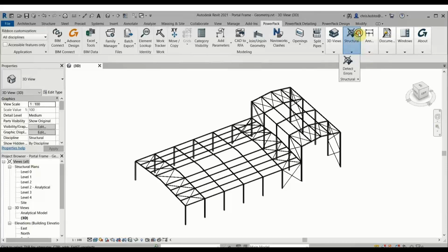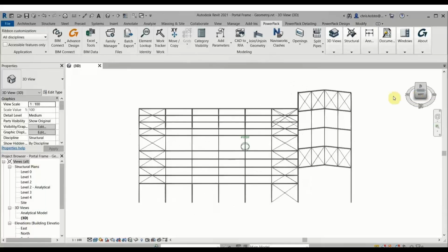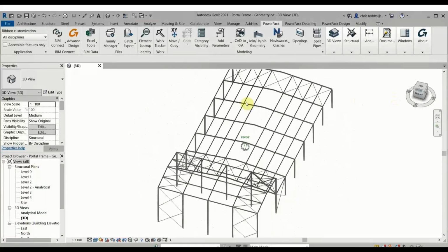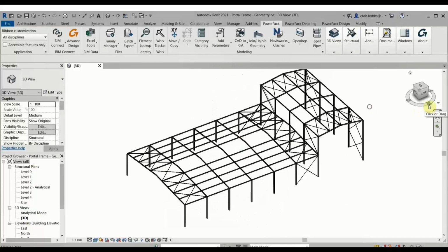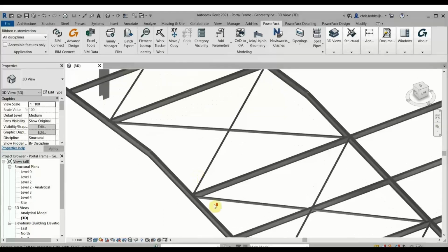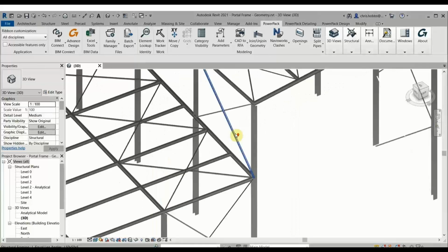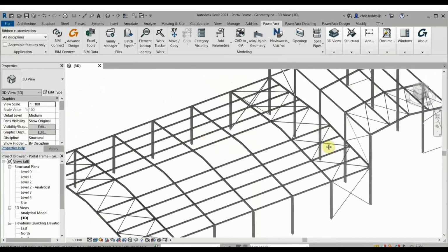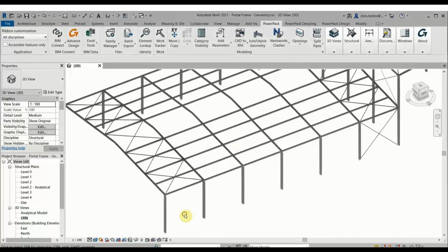So with the Power Pack, you also get the option to look at the structural analysis tools. Okay, so that's where you can verify any errors around the model. If I look around here, you can use the analytical tools to first of all find those errors where they are. They could be anything such as nodes not connecting, elements which need to be trimmed or extended. Sometimes we have elements which are not quite in plane. Sometimes bracing can be offset.